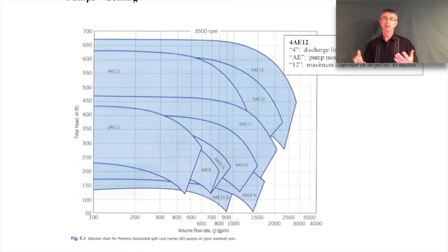So let's say you do that calculation and you find out, okay, a radial flow pump is most effective. It would be most efficient, I should say. And then you go to a company's website and they make many different kinds of centrifugal pumps, radial flow style pumps. And you need to determine from all these different model numbers what kind of centrifugal pump would be best for your application. So what companies do is they'll provide this kind of a plot that shows different model numbers. You can see here that are most appropriate for a given volumetric flow rate and head rise for your application.